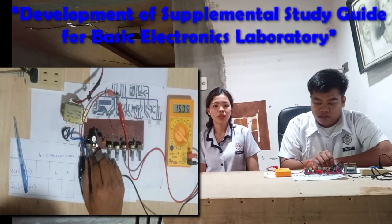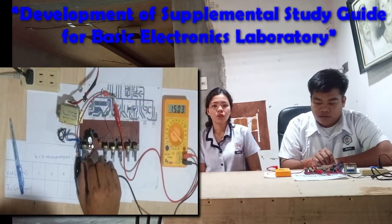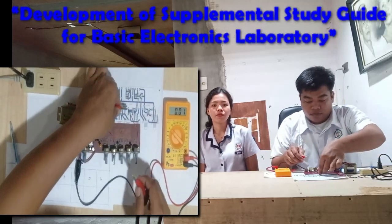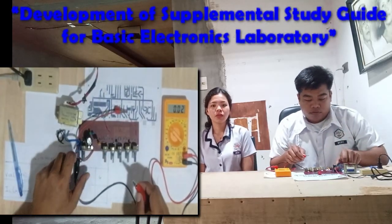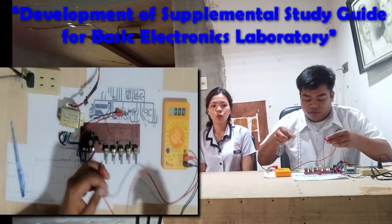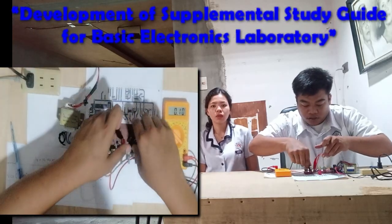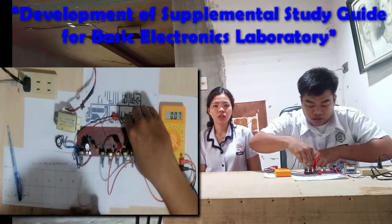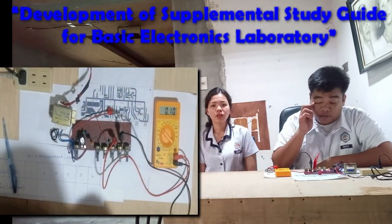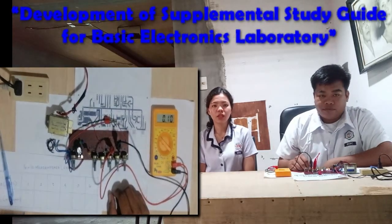We will now adjust the transistor base current to a value of 10 microamperes. To do this, we must turn potentiometer R1 slowly until the voltage across R2, measured with your multitester, is equal to 0.1 volt. According to Ohm's law, the current through R2 must now equal 0.1 volt divided by 10 kilo ohms, or 10 microamperes. Since this current also flows through the transistor base, the base current must equal 10 microamperes at this time.